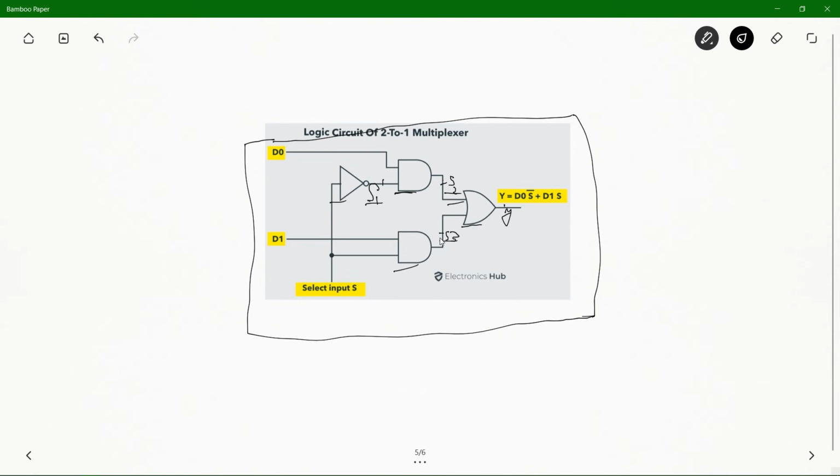And S3 is the output of my second AND gate and that is becoming the second input of my OR gate, right? And here I have named the final output to be Y, and I am naming these 2 inputs I0 and I1, right?